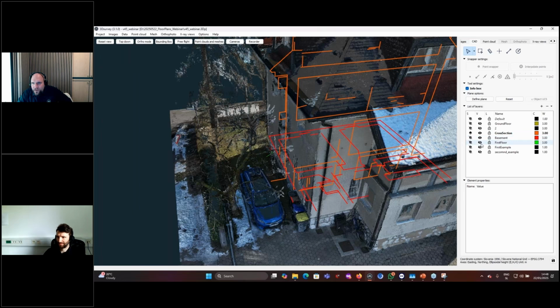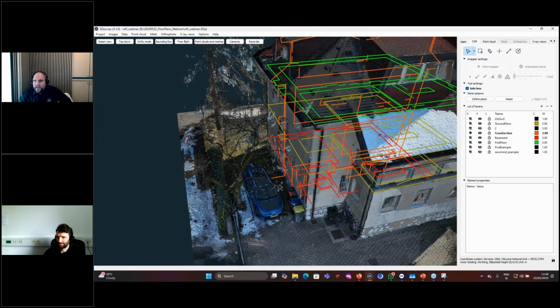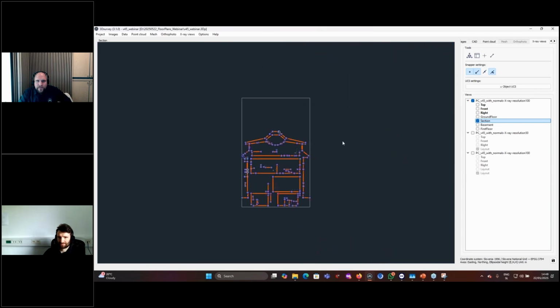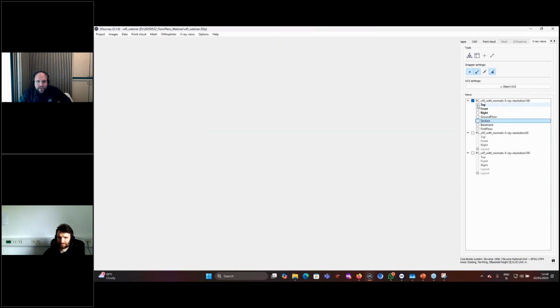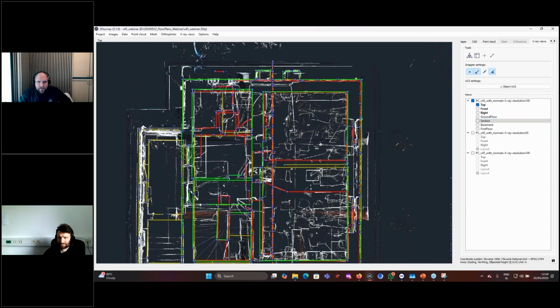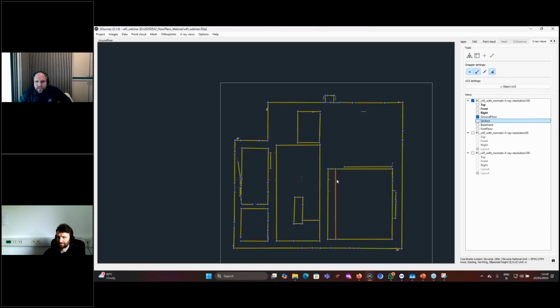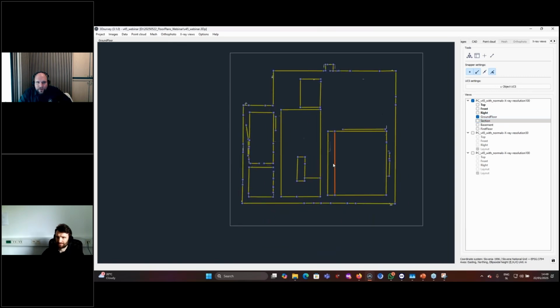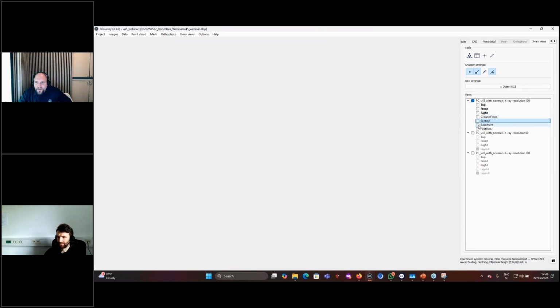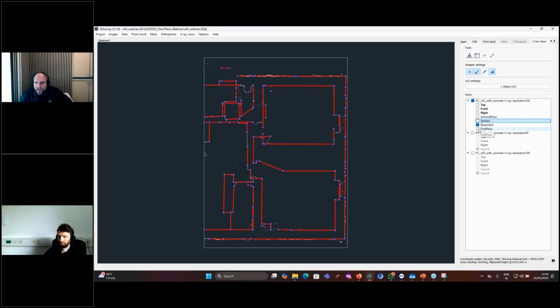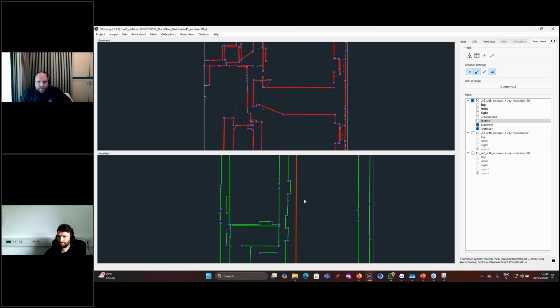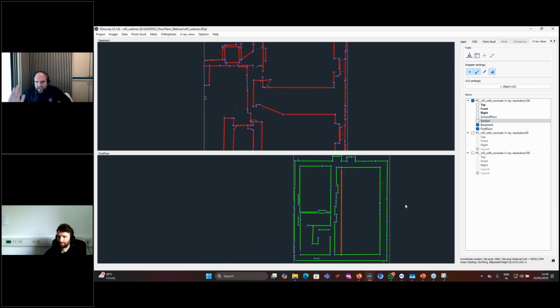And we have here also our basement and first floor and ground floor. And if we go to X-ray views, and now disable the section, enable the top. So here we now have the views together. If we go to ground floor, this is our ground floor. And here we see a bit of a section view and our basement and our first floor. And you get the idea. Maybe you will need to edit those lines a little bit, but it should save us a lot of time and energy.